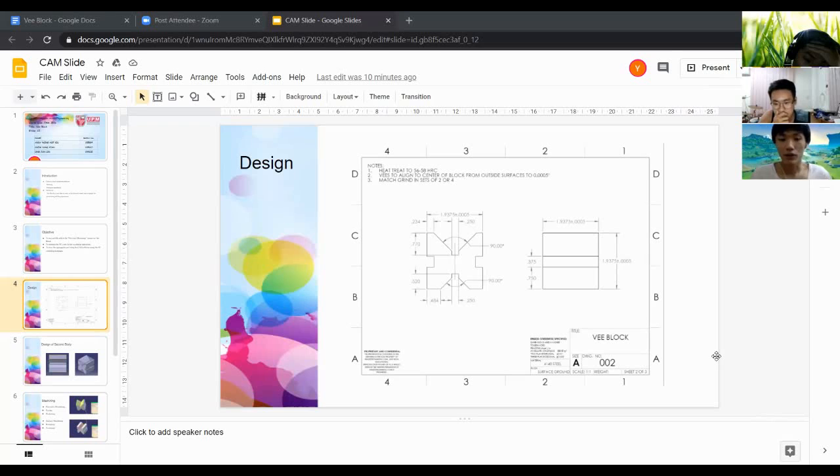And next we'll do the side hole, which is 0.375, as we can obtain from the right view. On our right hand side there will be a side view, and the middle hole will be 0.375. Next we'll do mirror on the Y plane, and we'll get the entire geometry, which is the front view as shown on the left hand side.